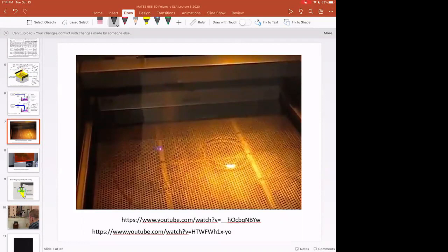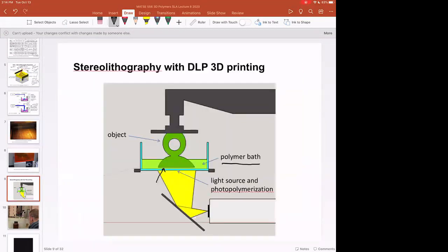And we'll talk about how to adjust the viscosity of SLA resins. You can add what are called reactive diluents, which are basically solvents that are monomers. So the thing that lowers the viscosity actually becomes part of the polymer chain, because you just can't add solvent to this. These are solvent-free processes. But I think there's a range of viscosities that you can work within, and definitely for top down, you can use higher viscosities than you can for bottom up because of the part release issue from the window.